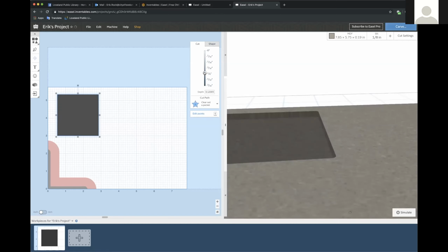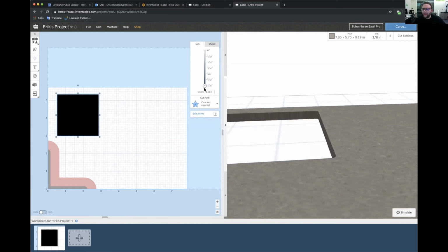So can it do that without wrecking the machine? Yeah, I'm glad you mentioned that. I'm going to explain that here in a little bit. So yes, it can carve all the way out. There are a couple things that we can actually do. So the first thing is the base board on Carvey, it's called the waste board for a reason. It is expected that you will make some carves into that without meaning to, or even purposefully, to be able to carve out some of these things.